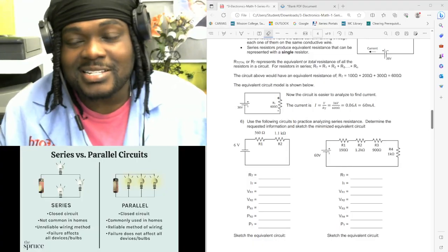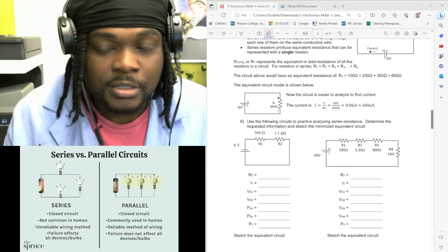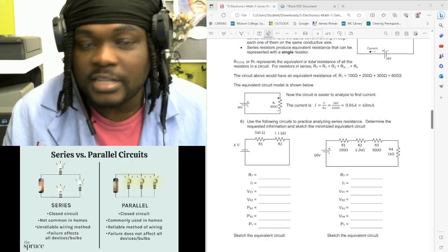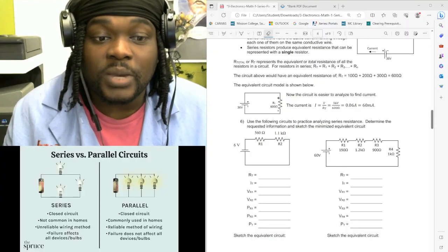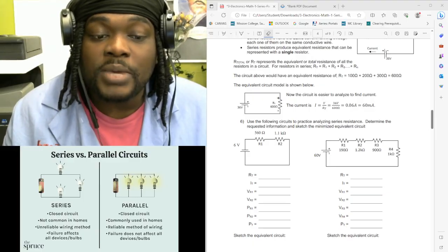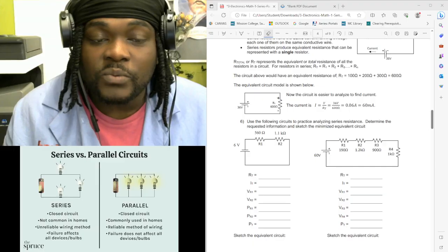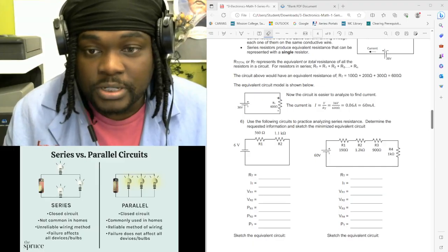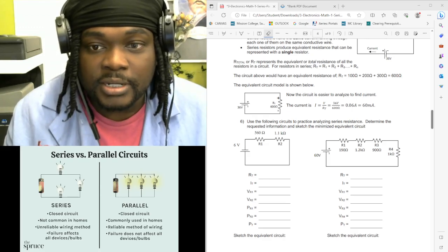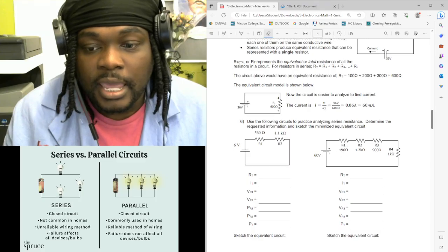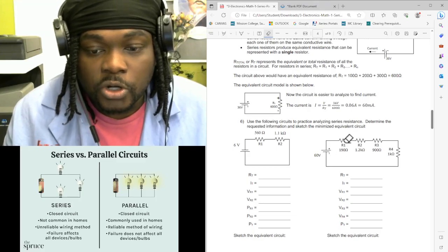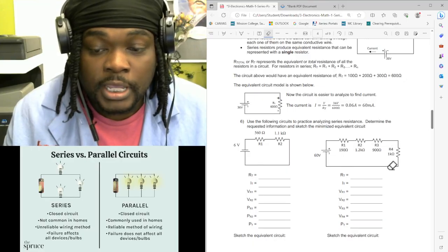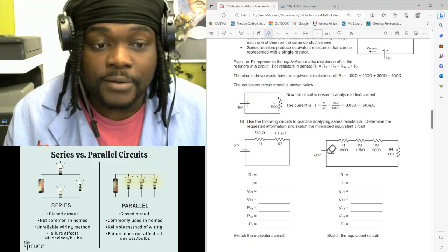Sometimes it gets a little bit tricky where people say, but there are these three things here, shouldn't they connect? But no, we have to remember that the reason this circuit is a series is because the current leaves the battery on the right, goes through R1, goes to R2, goes to R3, then goes to R4, and then returns back to the battery, okay?